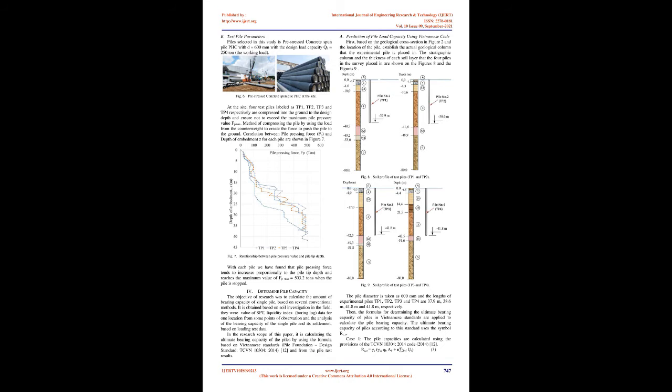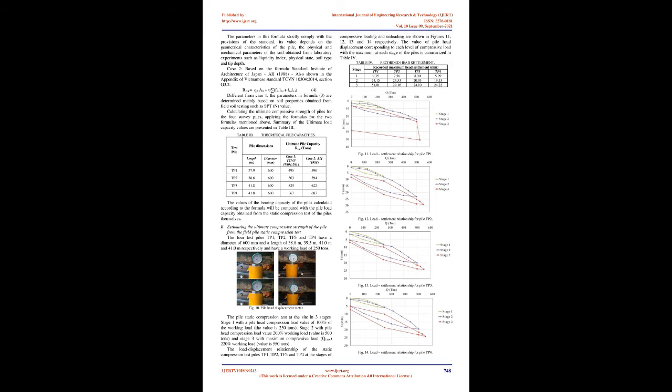In a number of documents and different standards, the results of pile compression tests have been explained and methods proposed to determine the ultimate load capacity from this test. J. Brinch-Hansen [4] proposed an estimate for calculating the ultimate bearing capacity. The Chin method of Brinch-Hansen 80% has the following simple relation, a straight line. Mazurkiewicz proposed a method of extrapolating load and settlement curves [5-6].